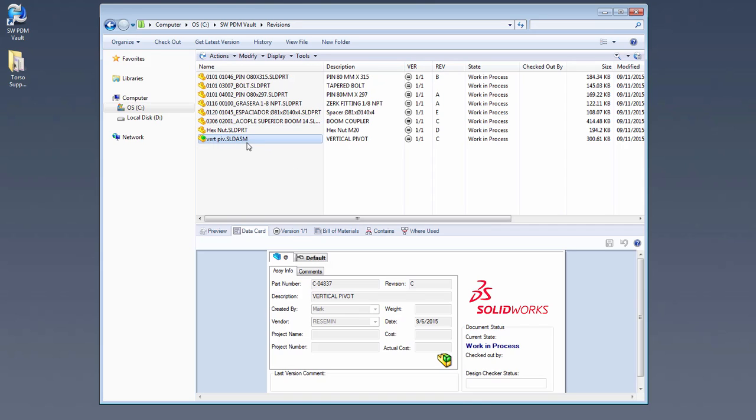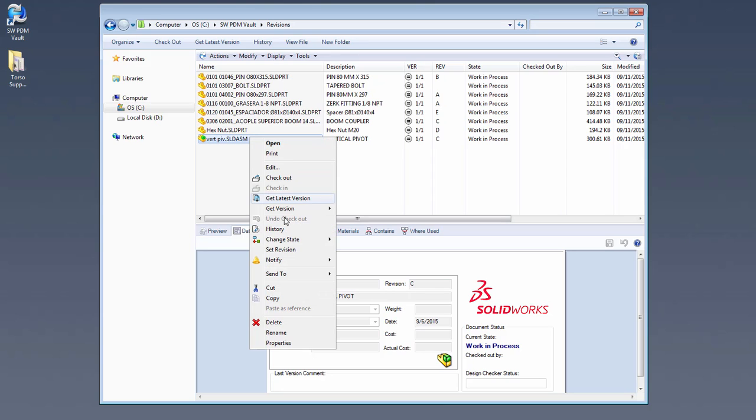Looking at the data card of this assembly, you can see that there are files with various revisions. Well, this assembly was imported into SOLIDWORKS PDM and has not yet been through a workflow. If you would run this through a workflow, the revisions would be automatically set to the first revision unless there was a complex workflow set up to handle this or you use the increment revision tool several times.